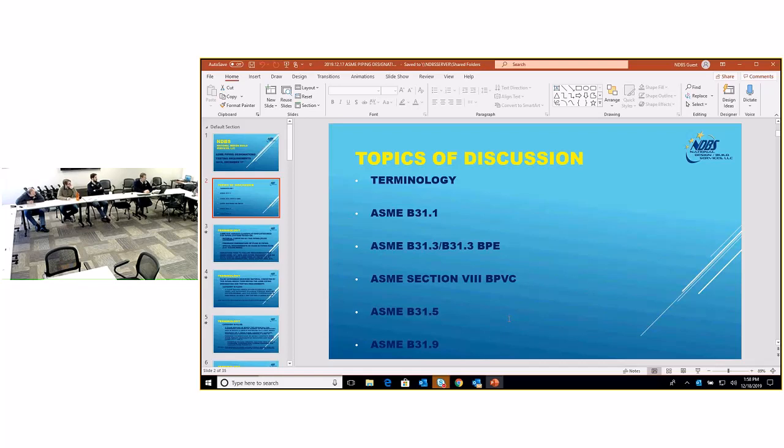So even if somebody closes the valves, there's no danger there, and to not have a pressure relief valve? I have it in writing from the owner. I happen to disagree with the owner in this case, but I have it in writing from the owner. Even if something doesn't heat up the fluids, if the fluids increase in pressure, it's stuff that'll still boil. That's correct. Must be one tough heat exchanger. It's a shell and tube, right? It is a plate and frame. Oh, it's a plate and frame? Are you kidding? My, you know, God.